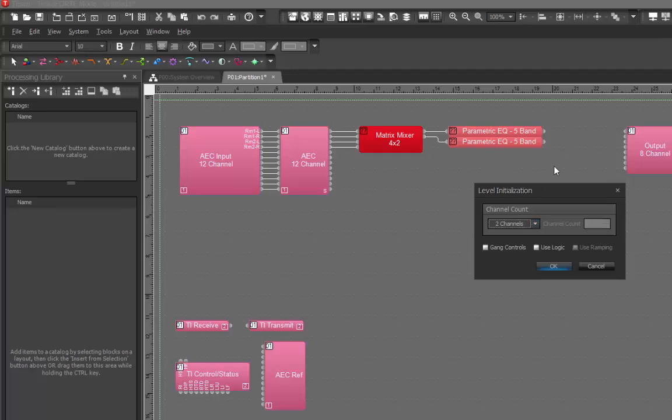So once it hits the Biamp, and this is kind of a hybrid system. There's other ways you'd do it where you'd actually have all your audio sources coming into the Biamp, and you'd be switching the audio in here and letting DMPS or whatever else handle the video. Okay. But in this case, just for simplicity, we're using DMPS to do all that switching, and this is basically just giving us level control and combine or uncombine. Now, if we didn't have to do the combine uncombine, we could use the DMPS for everything, because you can control audio volumes with that too.